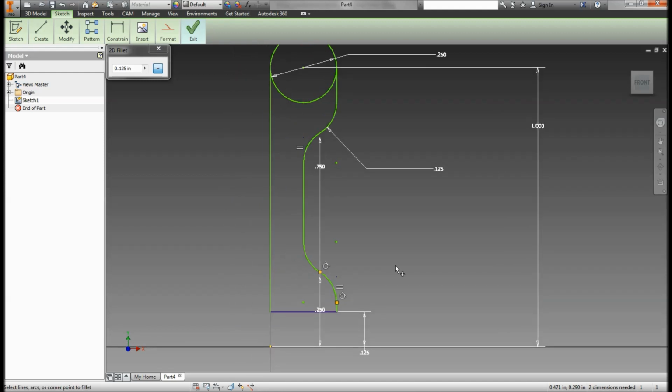Alright, let's see, what do we need to do next? We need to revolve this. And actually, I need to go backwards here. I didn't set my fillets to the right size. Again, looking at my drawing, I'll see that these fillets, or it shows one fillet, actually this one, measured at 0.0625, and you see that below the wheel it says R0.065, and below it says TYP.